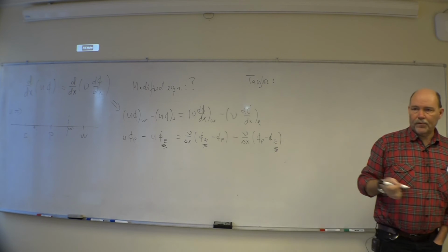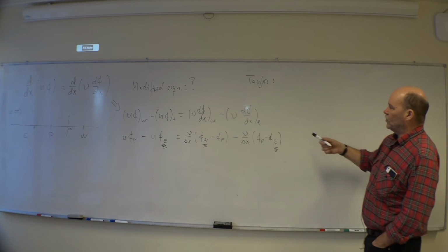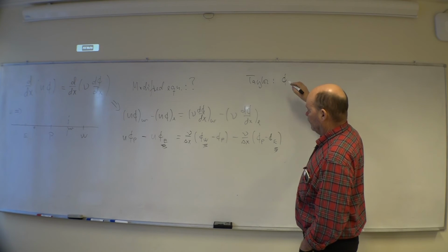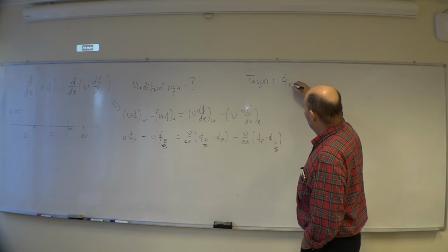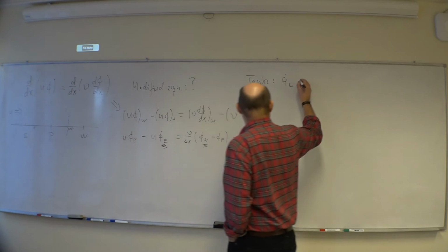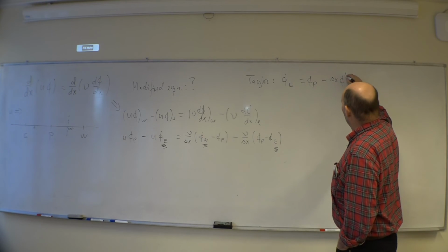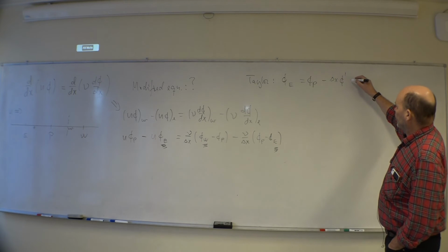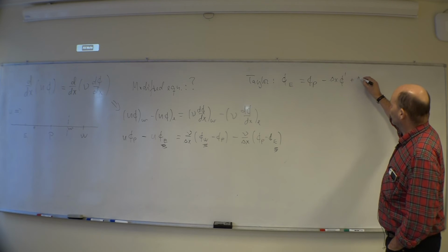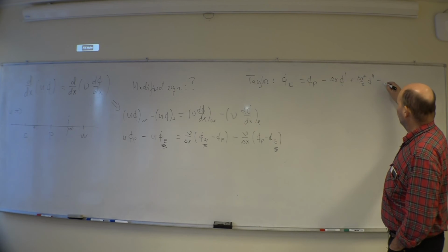So I mean, this is my point for finite difference. When you do the analysis, you go back to the finite difference world. So how can we express phi? We are going to need the eastern one. Well, there we have to use a negative Taylor series. So phi east equals center point minus delta x derivative, and then at the point p, plus delta x square half phi double derivative minus third order.